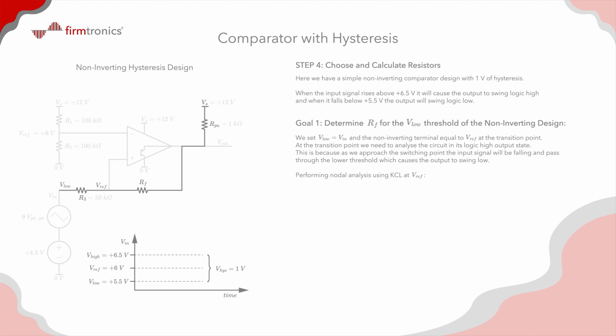So let's label the node currents with the red arrows to indicate the direction of current flow. Don't stress if you choose the wrong direction, as it just means the currents will be negative. However, you do need to be consistent, defining the non-arrowhead end throughout the equation as the higher potential and the arrowhead end as the lower potential.